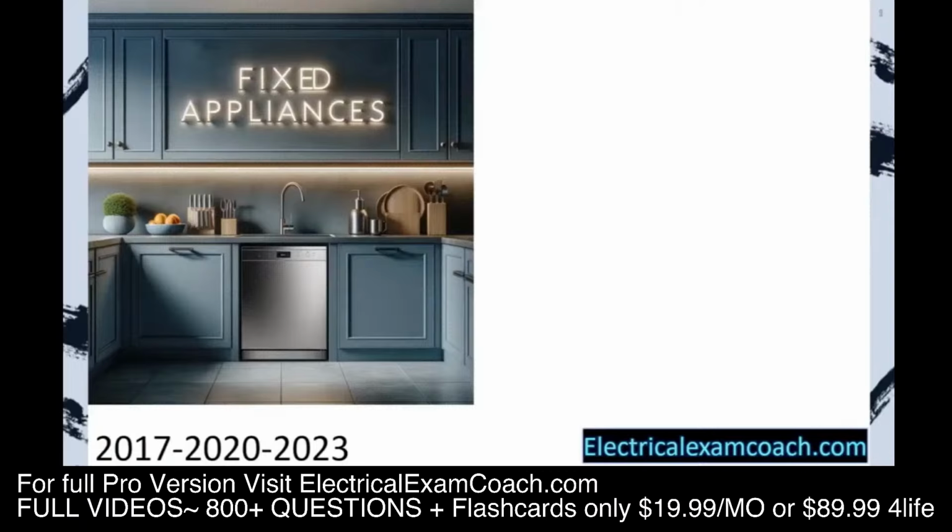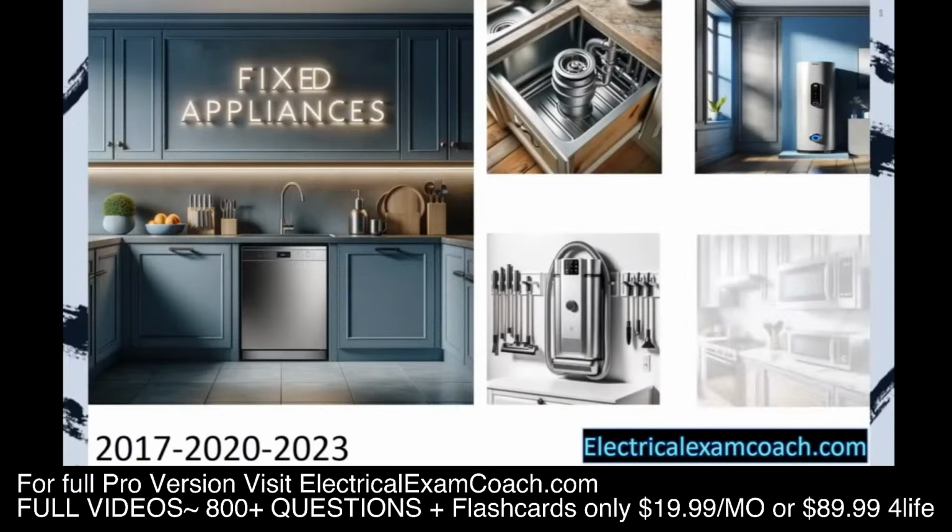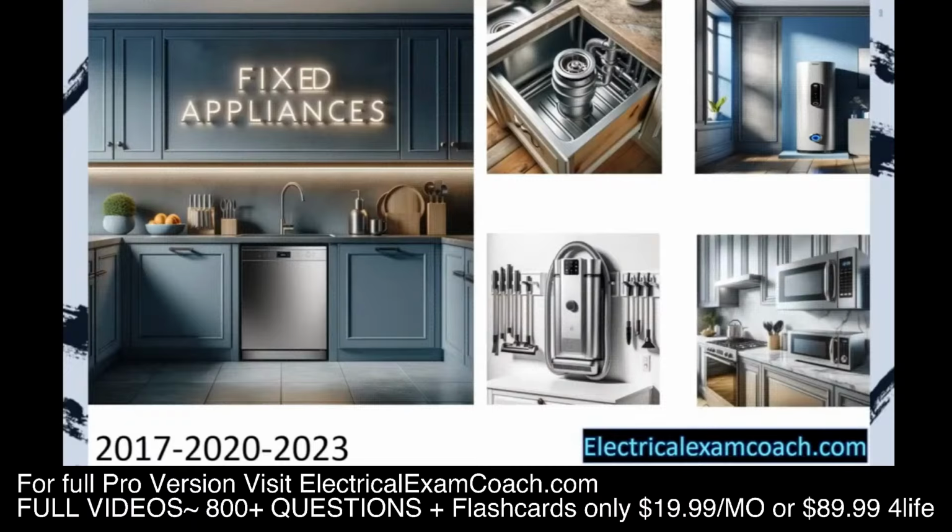Today we're going to be learning about fixed appliances and how they work into a whole house load calculation. Fixed appliances include things like dishwashers in this picture, but it also includes things like garbage disposals, water heaters, central vacuum systems, and microwaves, and pretty much any other appliance once it's fixed.